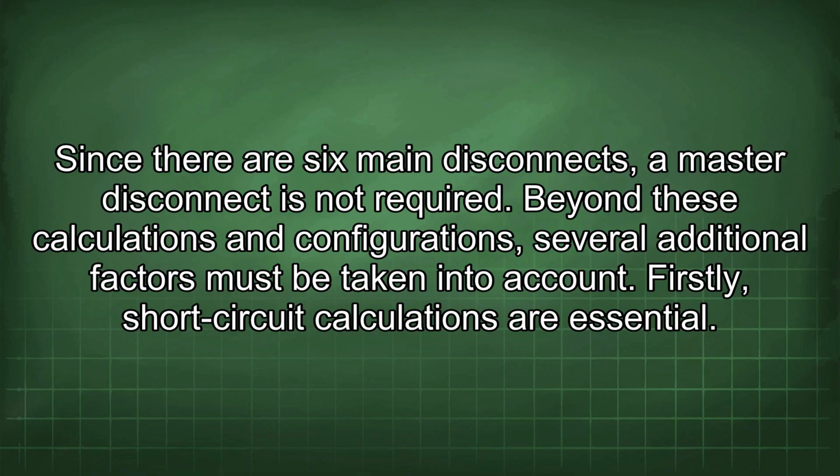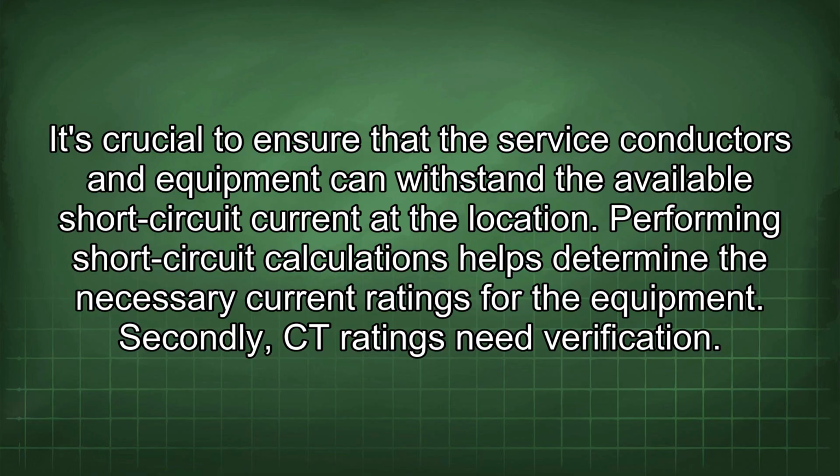Beyond these calculations and configurations, several additional factors must be taken into account. Firstly, short circuit calculations are essential. It's crucial to ensure that the service conductors and equipment can withstand the available short-circuit current at the location. Performing short-circuit calculations helps determine the necessary current ratings for the equipment.